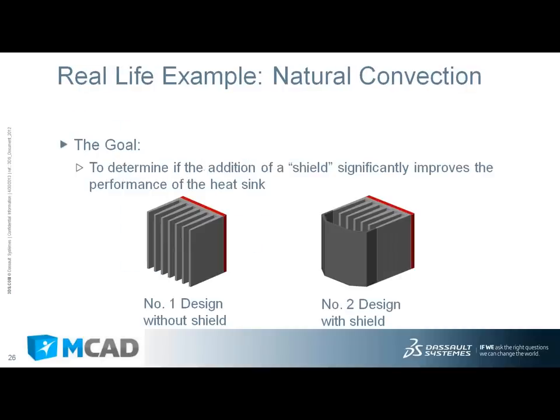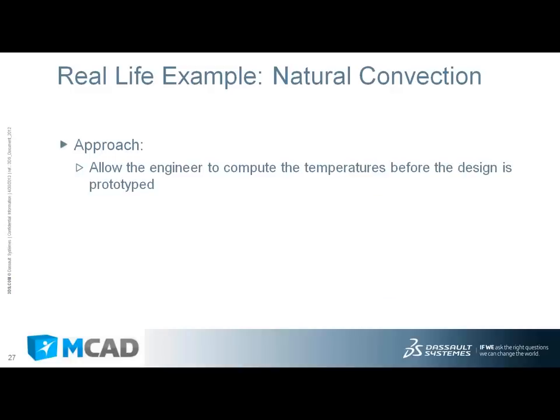A couple of, or one, modification that can be done would be to put sort of a shield on there to have sort of a chimney effect and funnel the flow, get a little higher velocity flow across the fins there. So let's look at some results on those two designs to see which one looks better.